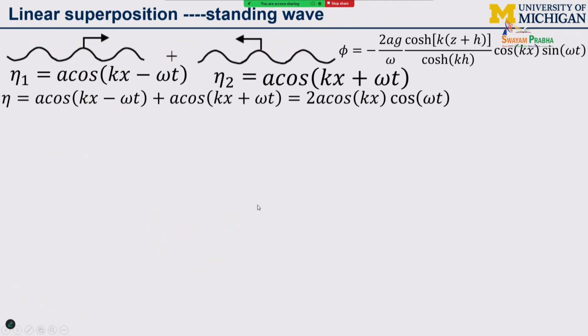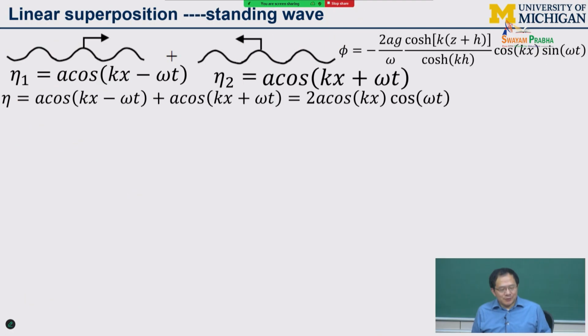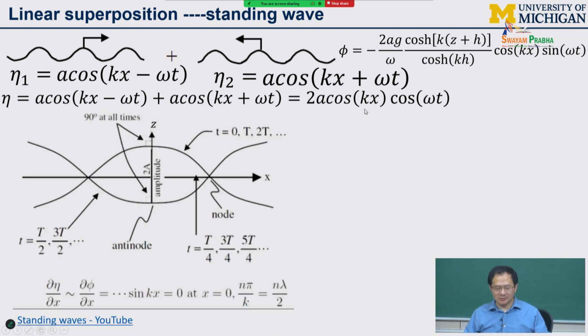Okay. So we are going to see some functions. Okay, one is linear superposition, right? You have waves going in different directions, and the wave frequencies are the same, and the water depth is the same, then k will be the same, right? Now the two waves, you add them together, and you go through the mathematical equations, you get this very interesting phenomenon.